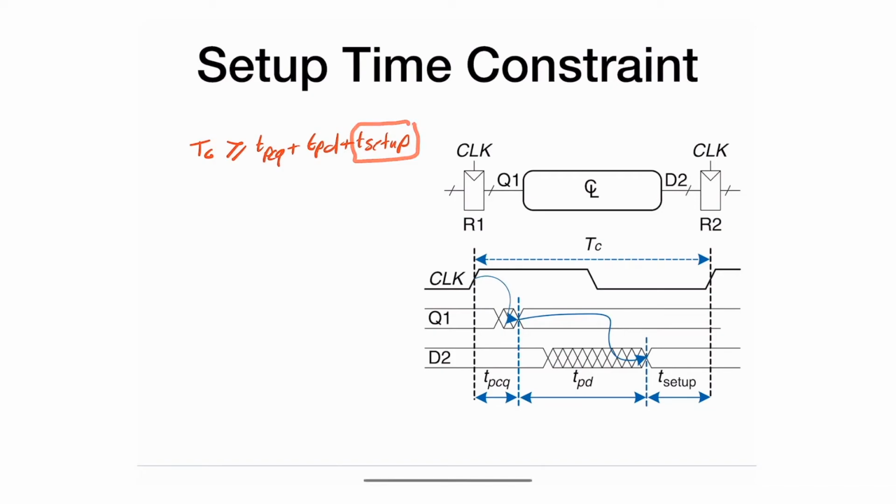Okay, so it's part of the flip-flop. The manufacturer of the flip-flop usually specifies it. The TPCQ, which is propagation clock to Q, is also from the flip-flop. So the same manufacturer decides this. Maybe not the manufacturer, maybe you decided to use a certain register that has certain specifications. So generally speaking, you don't have control over it. What you have control over is then this here and maybe here.